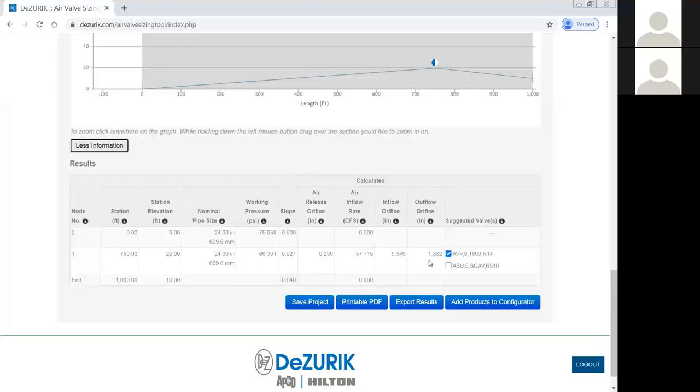Likewise, outflow orifice. Remember when we were filling the pipeline, air going out? This is the size orifice you would need for outflow. And as we've said before, usually inflow or vacuum protection is the more critical piece of information, and outflow is smaller than the inflow. So we just use the 6 and we're covered for inflow and outflow.